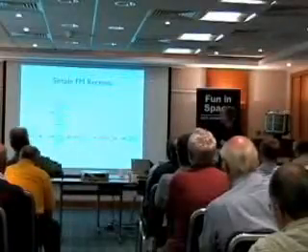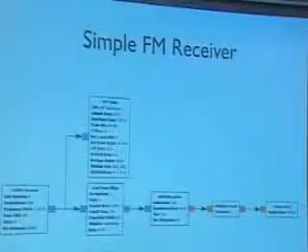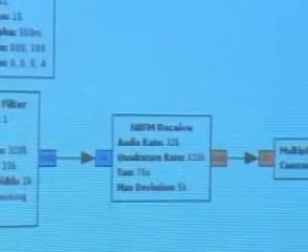The bottom graph continues through a low-pass filter, a block called NB-FM receive, which is actually a composite block built out of all the necessary parts: the de-emphasis, the demodulator, and an audio filter. And out of that, you have the audio, put in an audio amplifier, and out to the audio sink.